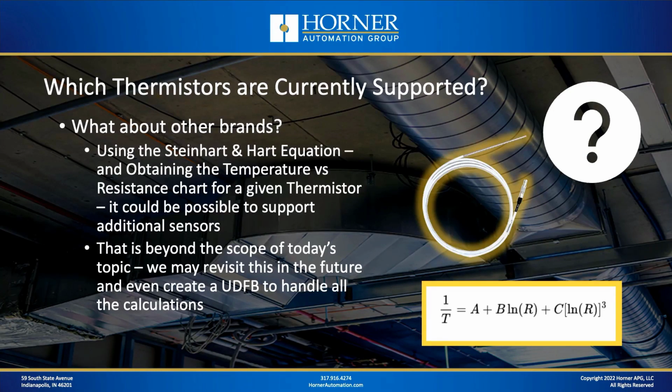Okay, now what about other brands? How could you potentially apply other brands with a Horner product that supports thermistors, such as an XL Series Model 2 special order, for instance? Well, in theory, you could use an equation called the Steinhart-Hart equation. If you had that equation and the temperature versus resistance chart for the thermistor you wanted to use, in theory, you could apply a mathematical equation and come up with a resistance to temperature conversion. However, that is beyond the scope of today's topic, but we might revisit this in the future, and I may even create a user-defined function block to handle all the calculations for you, but we'll see if that happens in the future.